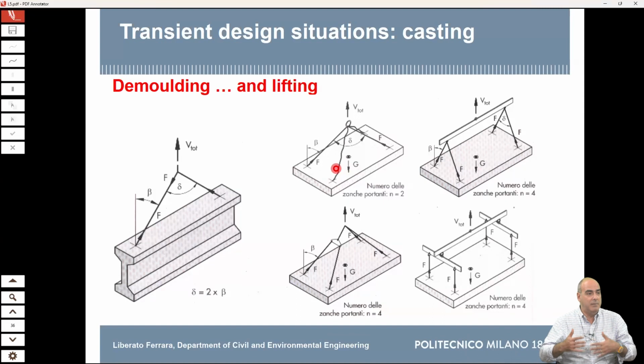So there will be some functionality requirements that will probably be reflected in the fact that if you have to apply some waterproofing, you will have an imperfect waterproofing, or if you have to apply some additional casting, half a centimeter of camber, of sagging, over 100 square meters of surface means that you have additional concrete to pour and level that you have not accounted for. So these are all issues that you have to take into account.